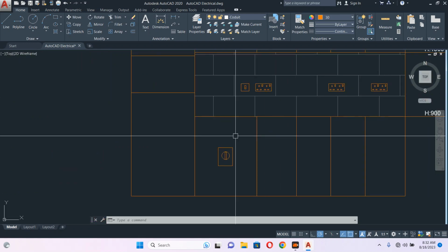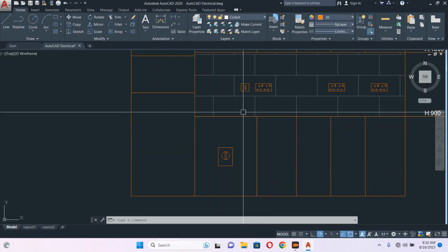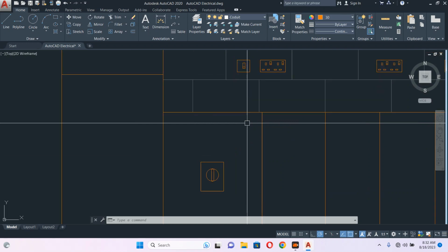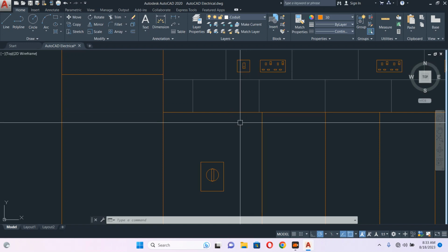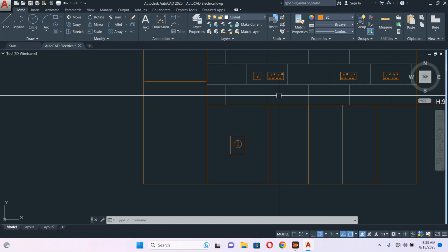So if it is a gas cooker and it has an electrical switch to trigger the fire, you have to provide a spare outlet. If a plug-type cable is available with the cooker, you have to provide one socket outlet.